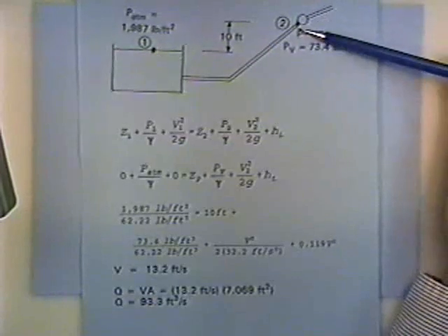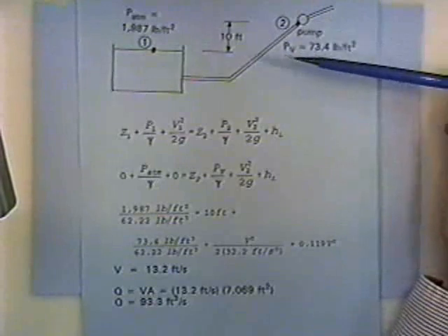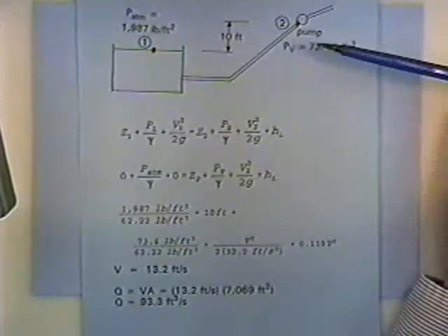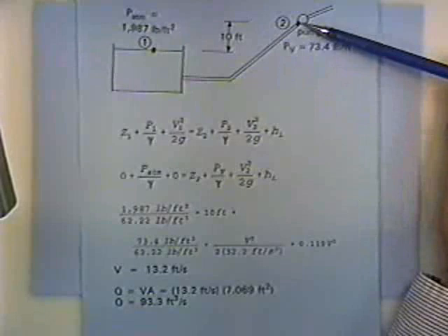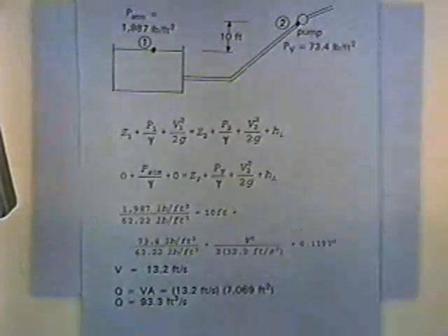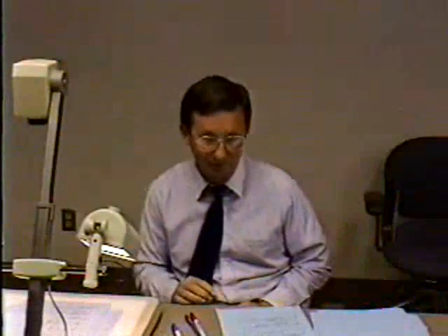Now, if you set the discharge, another good exam problem would be: for a given discharge, how high can you make the pump? Same thing, you're just solving for Z instead of the velocity in that variation of that particular concept.